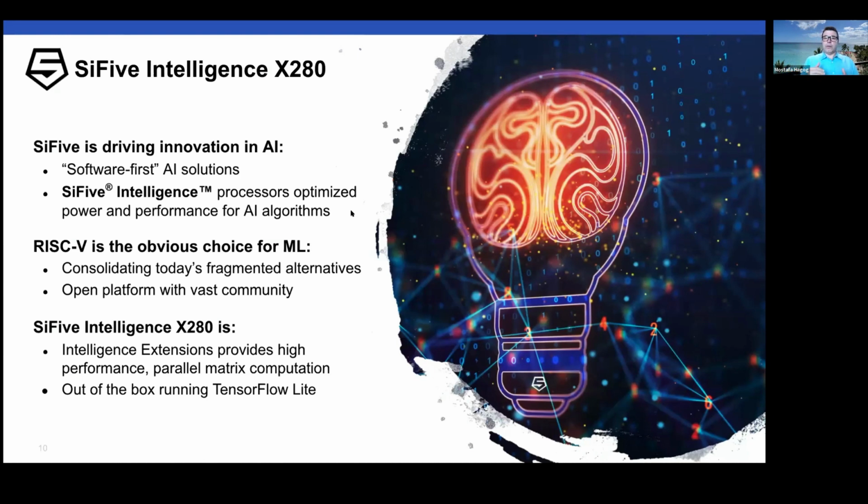As we analyze more and more workloads, the way we approach the problem is that we look at the workload end to end. What's the benefit of the numerics? That's why our focus for inference is actually using int8 and not bfloat to optimize these workloads. Bfloat is well regarded in the training domain. If there are other data types that we see could be used once we tweak the design, we could use these other floating point representations. It's really about what benefits you, what is the trade-off between the ROI, how much investment in the area and the engineering complexity, and how much benefit you can get out of that.